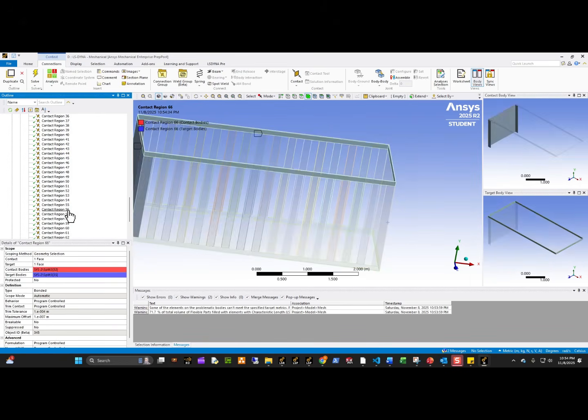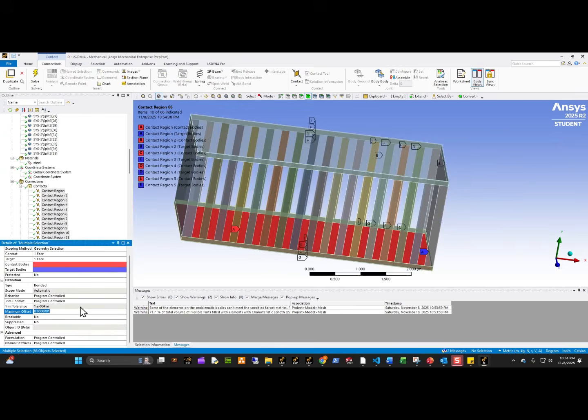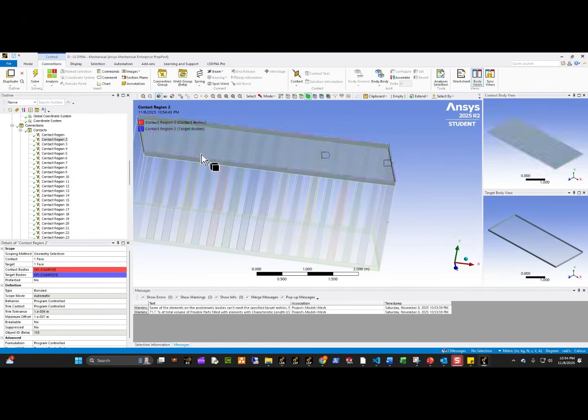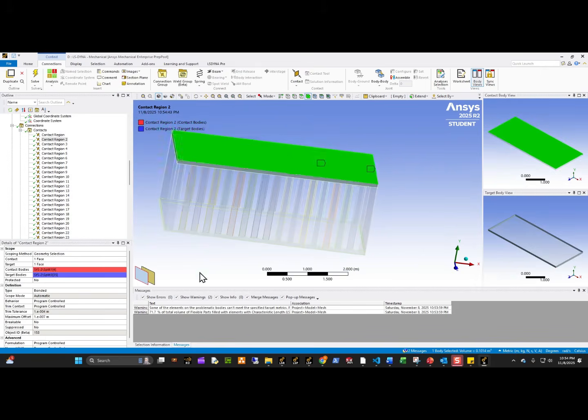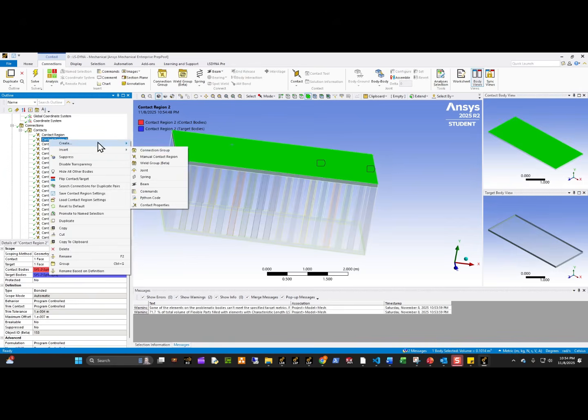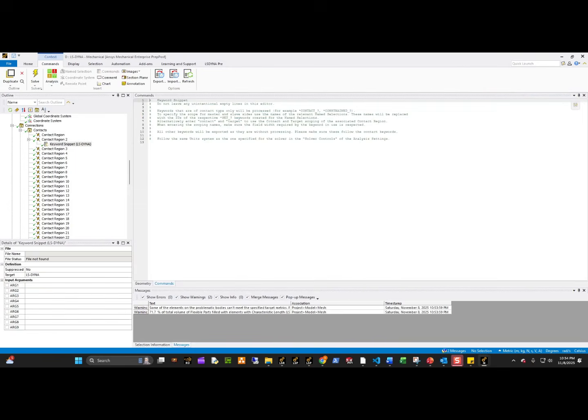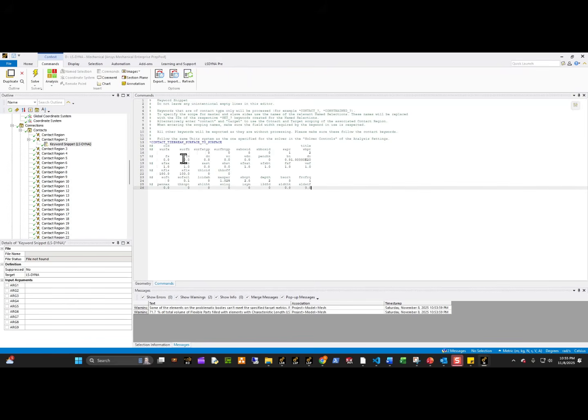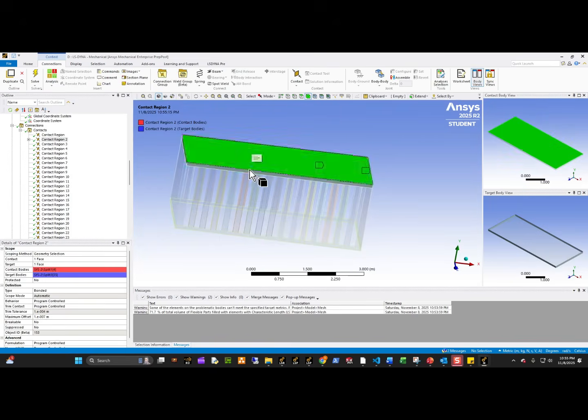Yeah, it should. And then what I wanted to do here is, these are all basically contact meshes, and I'm just going to do, yeah, this is fine. The only thing that I want is for this one to have a tie break contact, because I want the top to basically blow open, which is what I have in my original model. So I'm going to insert a tie break contact from my keyword template. You see I have this space here empty. That's going to take these two surfaces and put them into this card. And there I have 100 megapascal as the contact pressure required to debond this top board.